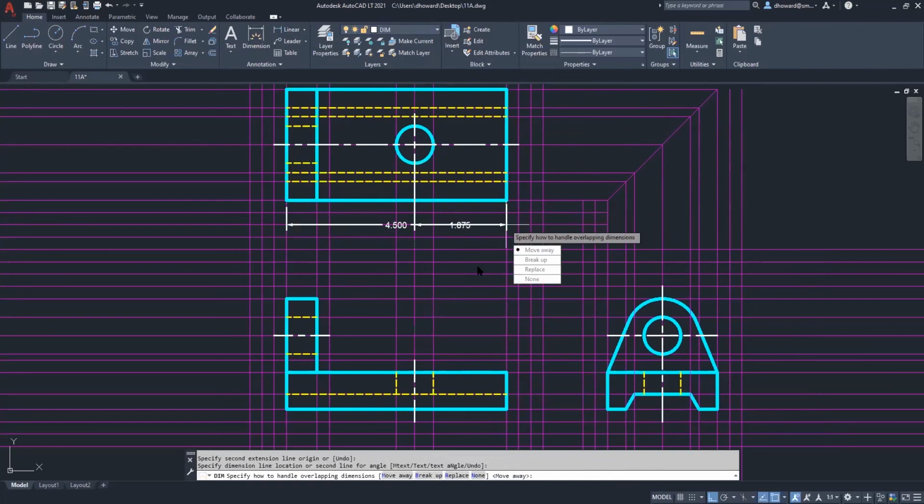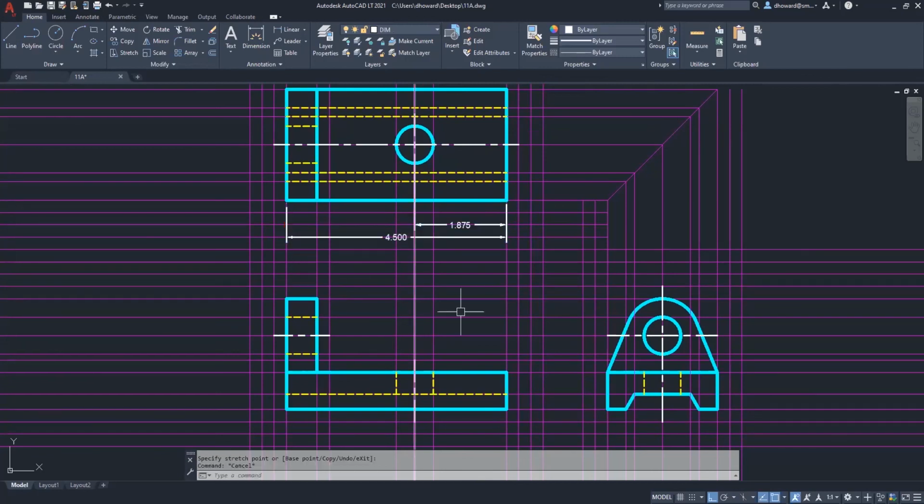So if that one is to go there, then this one should probably go beyond that. And you can see the spacing. Again, the first offset of 1/4 inch is reserved for center lines, and then beyond that, the first dimension, and beyond that, the second dimension.